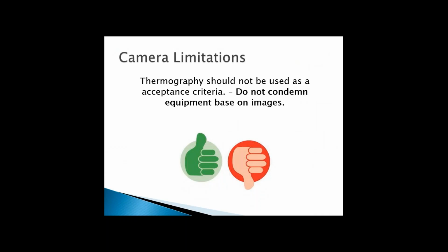Another really important limitation that you should consider: you should not use thermography as acceptance criteria. Basically, we shouldn't use the pictures that we receive from an infrared camera to condemn equipment based on the images. It's accepted best trade practice to gather information using the infrared camera and use some type of secondary method of verifying your assumptions. So we shouldn't use this camera for a no-go or go scenario.